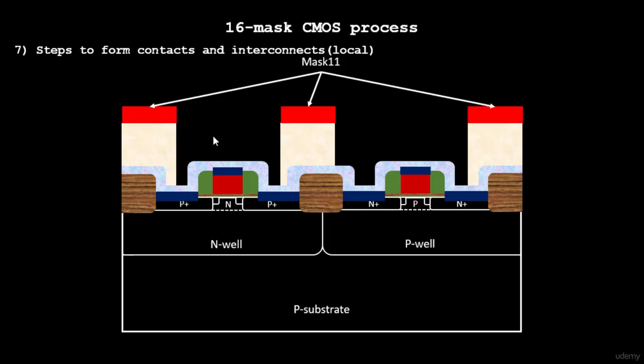We will now remove the mask which is present over here, and expose this structure to arsenic. There are two types of negative or N-type impurities that we have been talking about: arsenic and phosphorus. Let's go with arsenic at this point. The amount of energy needed is 75 kilo electron volts, and this will go right inside over here, and the side walls over here, which are actually the sidewall spacers, and the reason that we have added the sidewall spacers is to keep the LDD intact.